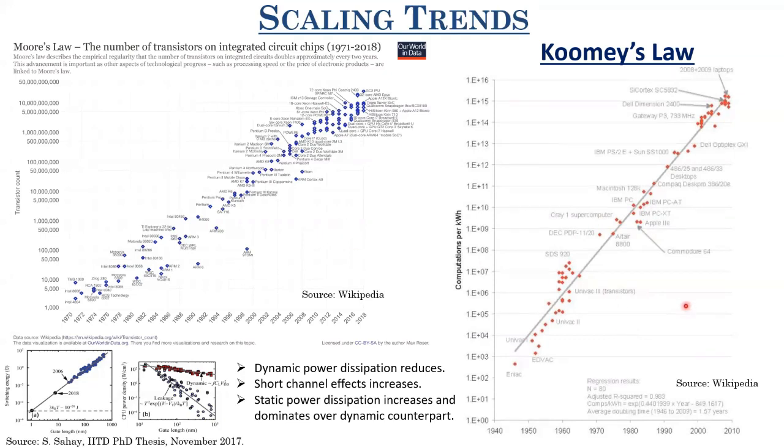Now with this fundamental understanding of the scaling, let me talk about how cache memory actually affects CPU performance. We saw that cache memory is used for creating local copies of data of the main memory, so that your processing core doesn't have to communicate with the off-chip main memory every time. This local copy of the data helps you achieve very fast speed of operation, right? So this is one way in which cache memory affects CPU performance. That is, it increases its speed. Is there any other way? Does it also affect the CPU's power? This is what we'll discuss in this slide.